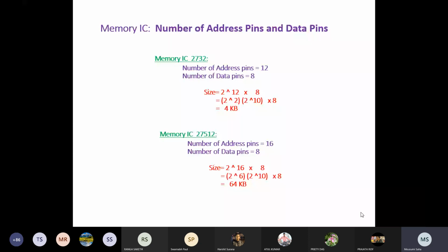Now suppose you consider one memory that has 12 address pins and 8 data pins. How can you compute the size? That is 2 to the power 12.